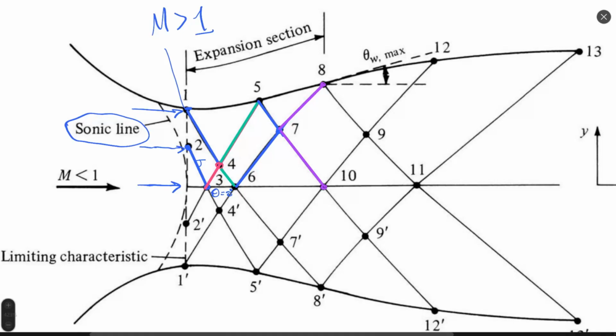The method of characteristics is good not just for this calculation of points on the wall or inside the flow, but the method of characteristics is also used to profile the nozzle. To profile, not just to obtain flow properties. How can profiling of a nozzle be done? What is the idea? The idea is simple, that the profile of the nozzle should be built in a way that it will not generate any change of entropy, or it will not produce any shock waves. So we have to preserve isentropic flow structure inside the nozzle, and in such a way we will obtain the shape of the nozzle.